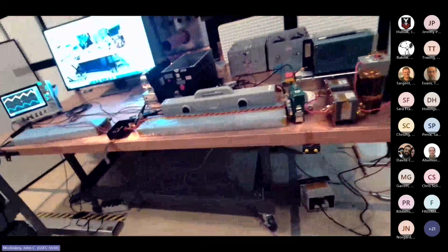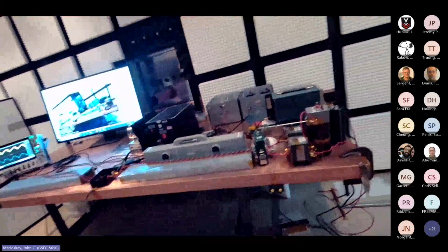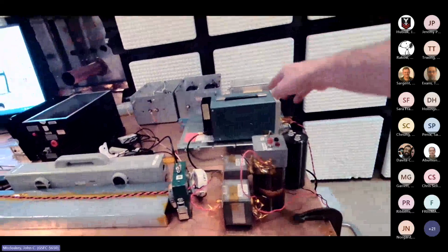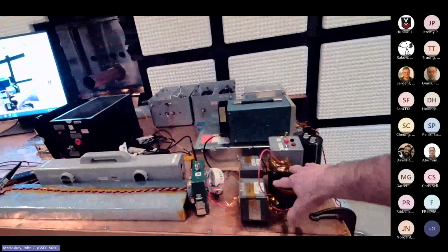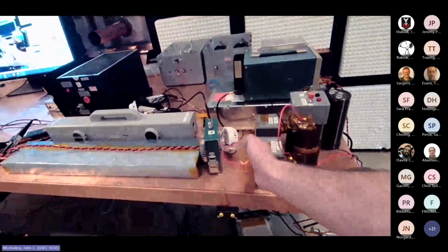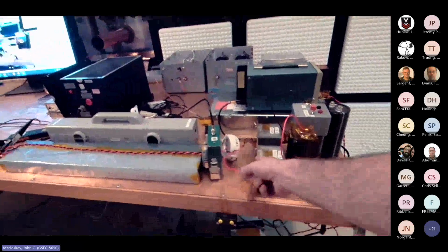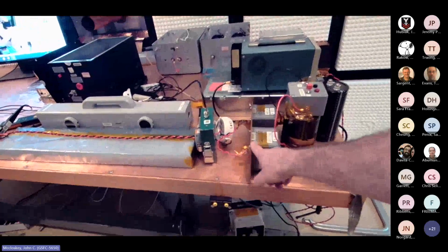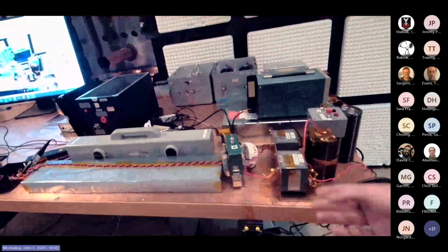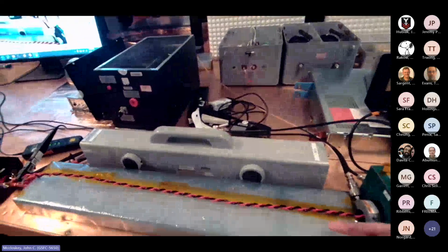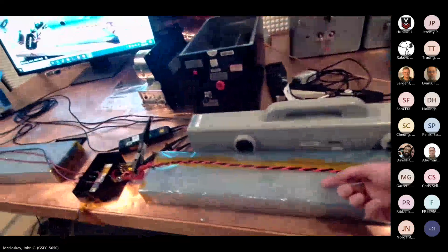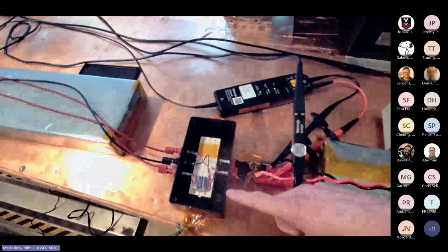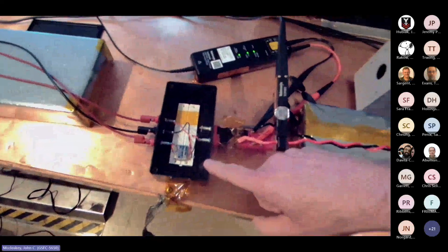So just getting a broader look at our test setup here. We have our power feed coming through the capacitor network to decouple from the power supply, give us something that looks like a battery, a source impedance at this point that the EUT sees that is very low impedance, with these capacitors representing a battery. So what is it we're testing? Well, we have the power leads now run as a twisted pair going to this intentionally unshielded and unfiltered power converter.